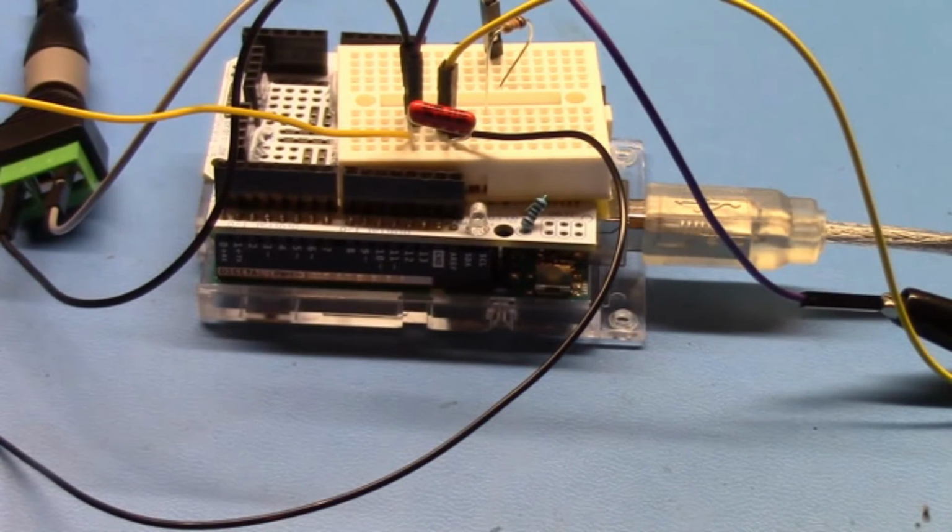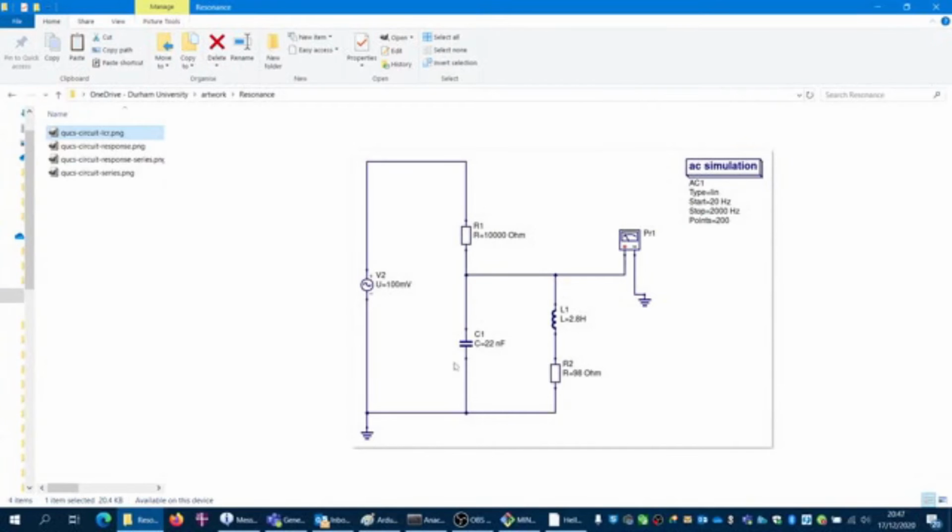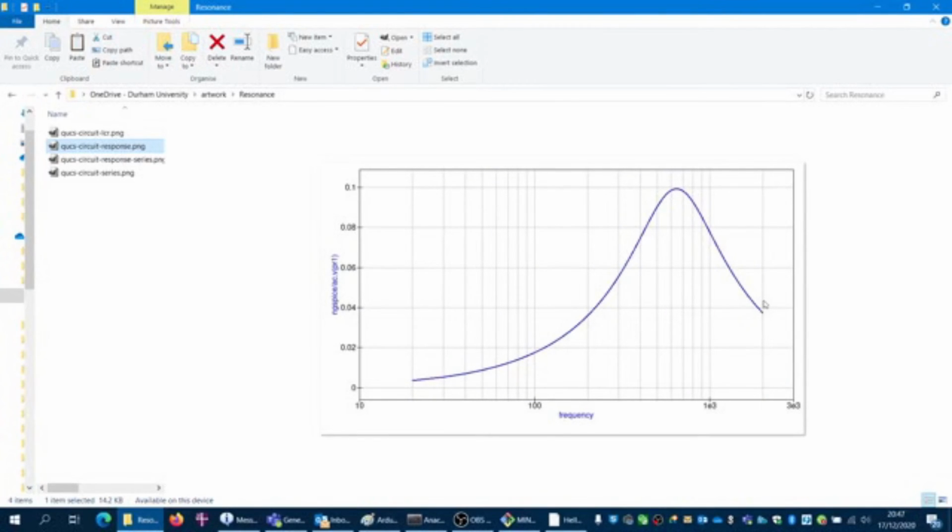So that corresponds to this case where you've got a capacitor in parallel with the inductor, and in this case you've got the same voltage across each because they're both connected at each end, and instead the current splits a certain percentage that way, a certain percentage that way. Again ignoring R2, at resonance the reactance of each is equal, so the current is split equally but 180 degrees out of phase with each other. So you would essentially at resonance have 0 current flowing through this combined network, and so the voltage at this point will rise up to the supply rail. Instead of seeing a dip, you should see a peak up to the supply rail voltage at resonance, which should look like this for the values I've chosen.